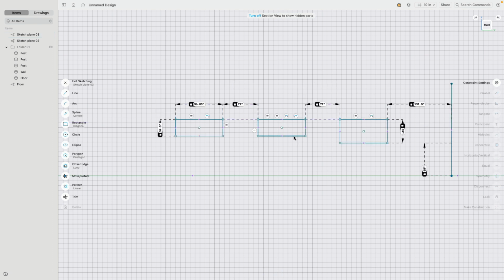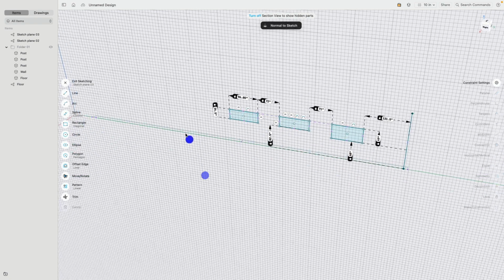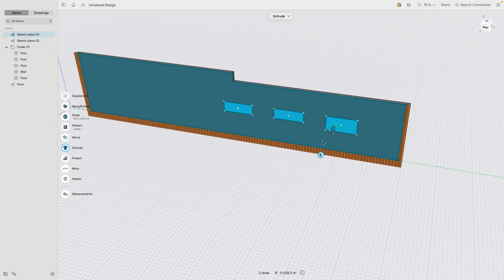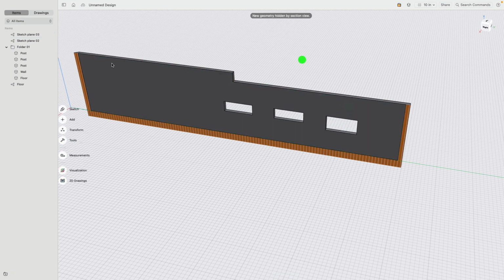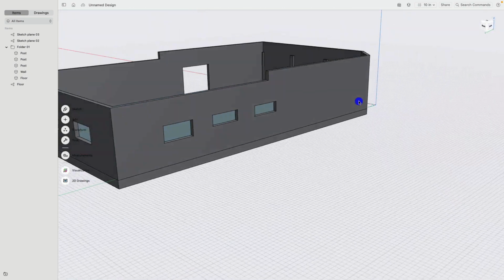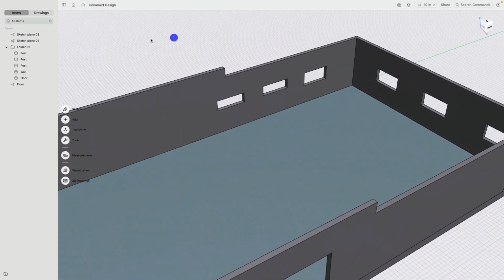Put it on. To verify, this point to here, and vertical should be, yeah, 82.5. Okay, that's correct. We can even put this in for display purpose. Very good. Okay, very nice. Yeah, that's all what we need. Then exit sketch, turn on this, select our profiles, click and drag, cut through, turn off the section cut. And you see, now very quickly we're going to model the space.